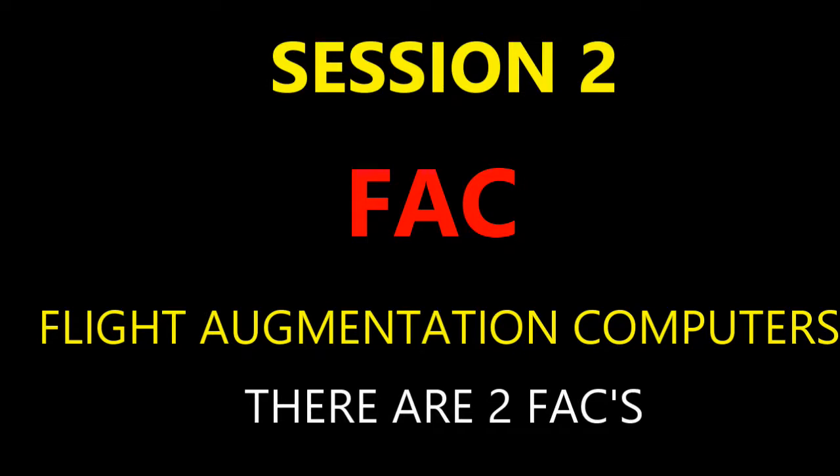The one thing that's not is obviously the push button for the FAC, that's coming from the flight augmentation computer itself. So that kind of goes without saying. But the different kinds of warnings: besides the wind shear, I mentioned low energy warning, which has the flight path angle as a function of it. You've got current speed and acceleration rate. So when I describe how aircraft energy is defined, it's a function of current speed, your flight path angle, and your acceleration rate.